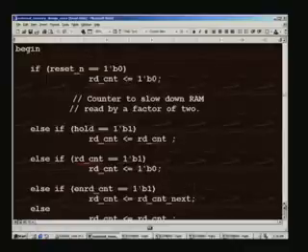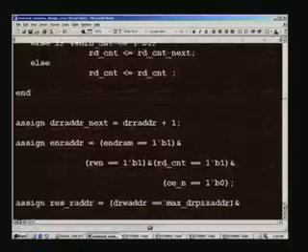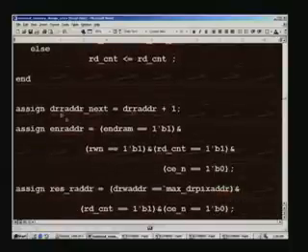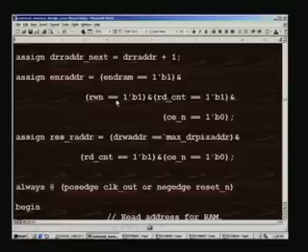It keeps on toggling by these two expressions here. It is exactly the same as write counter. And once again assign statements are there for read address, and it is exactly the same as write address we have seen before, and exactly matching condition except for the fact that read is 1, that is in read mode, and earlier it was 0 for the write address.